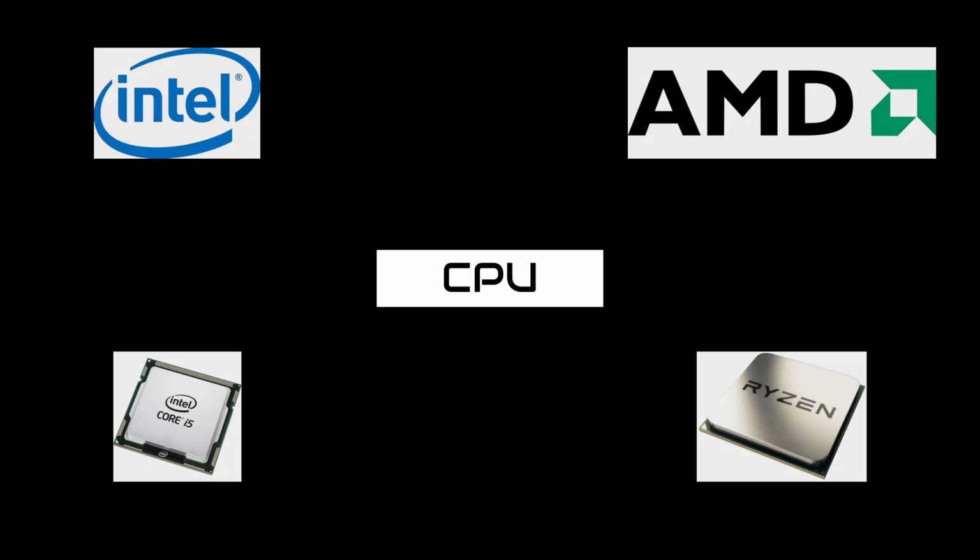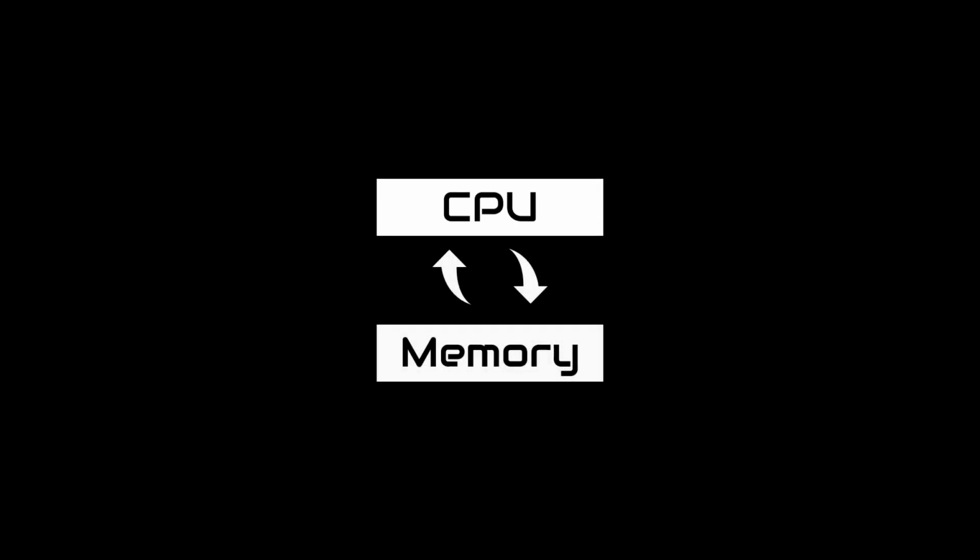At their core, processors do the same thing. They grab some data from memory, process it, and put it back into memory. But there are a few specifications worth noting. The amount of data a processor grabs from memory is the word size. A 64-bit processor grabs 64 bits of data from memory every cycle. This is different from 64-bit programs. A 64-bit processor can run 64-bit or 32-bit programs, but a 32-bit processor can only run 32-bit programs.